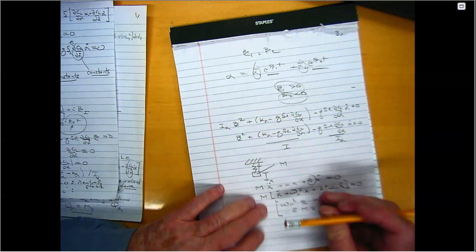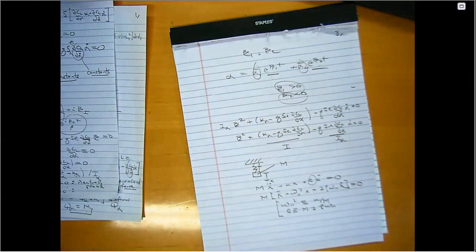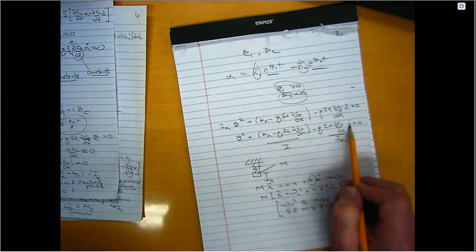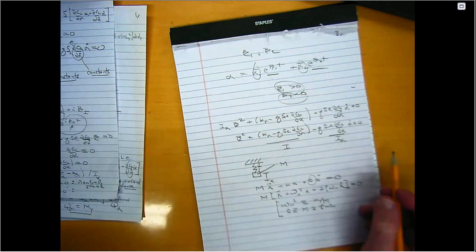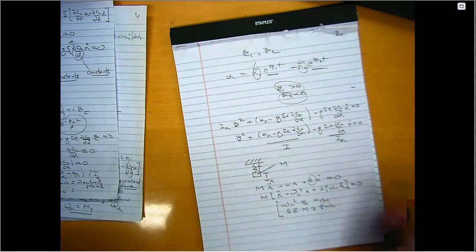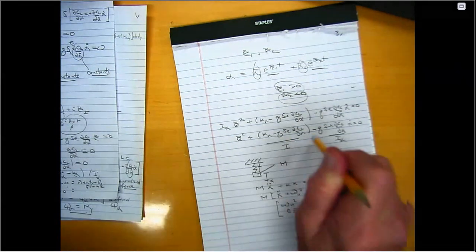Okay. So you've all had occasion to take Professor Keel's vibration course. You probably looked at this example, right? Well, our equation is essentially the same equation. We have a spring, except it's a torsional spring. And we have an alpha dot term, which arises from the aerodynamics, not from some dashpot oscillator. And so all the things we know about this equation can be used to interpret that equation.